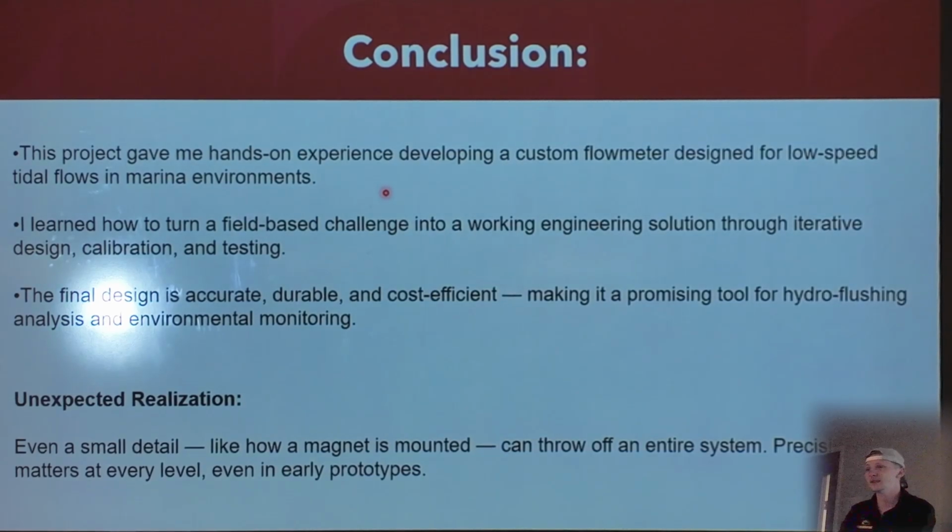One of the unexpected realizations that I had throughout the semester was even small details like how a magnet is mounted, or where the Hall effect sensor is, or how it's potted or placed, can throw off the entire system, especially when a detection range is millimeters apart. So I did learn that precision does matter at every level, even in early prototypes, and you should take every factor into consideration.